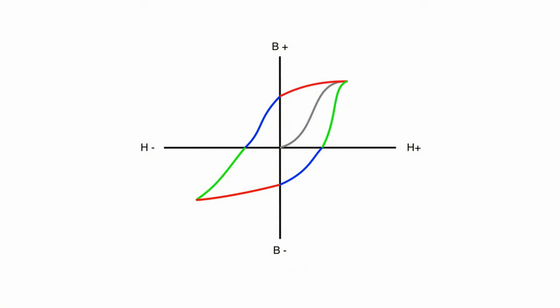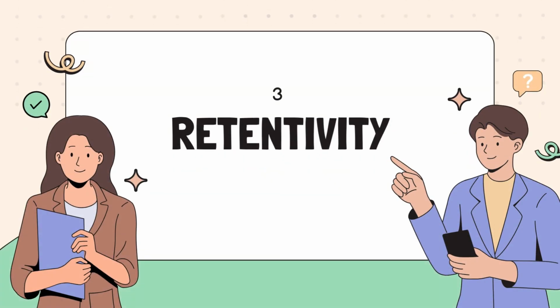Whereas if you're trying to create a big, huge electromagnet, you want to have it kind of come up top here. So what we talk about is how a hysteresis loop for an electromagnet, something that you want to have retain its magnetism, is going to be relatively large or fat compared to if you have an iron core or something for a transformer or a relay or a coil. You want that to be skinny. So as soon as you get rid of the magnetic intensity, that's going to drop down closer. Let us discuss retentivity now in details.